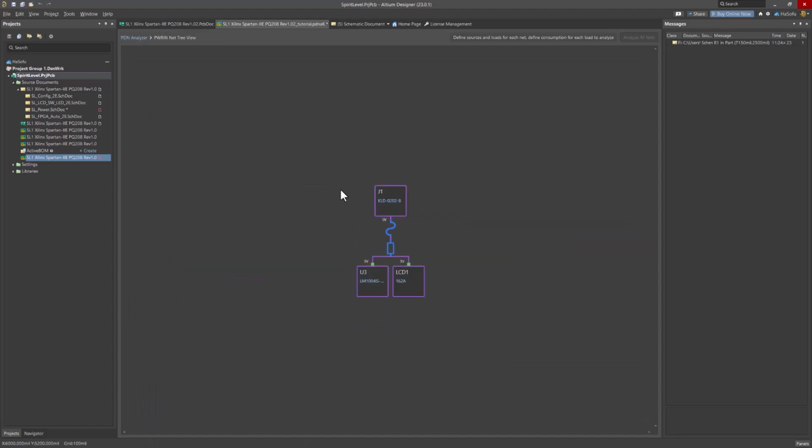See the top of this voltage regulator analysis tree, that J1 connector, it goes to that fuse and then the switch. Then its two loads are the two voltage regulator modules. We've got the U3, which is the voltage regulator module, and then the LCD, right? And we need to add another voltage regulator module, the U4, which outputs 1.8 volts. But I'll show you that in a bit.